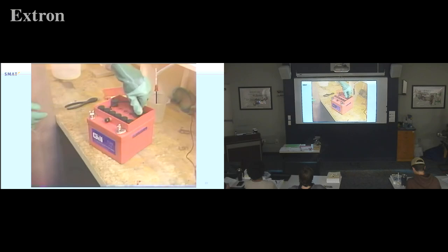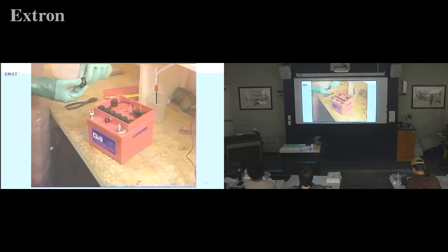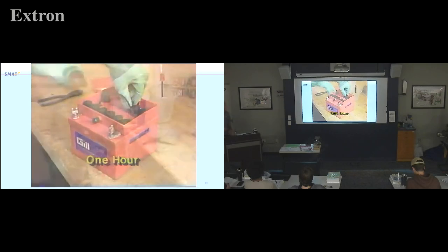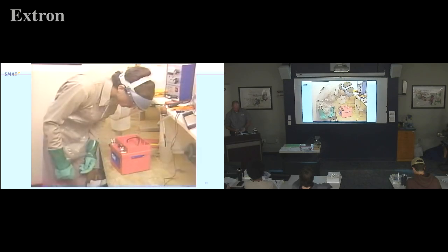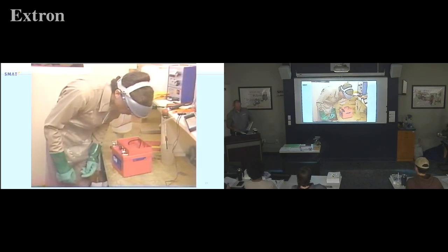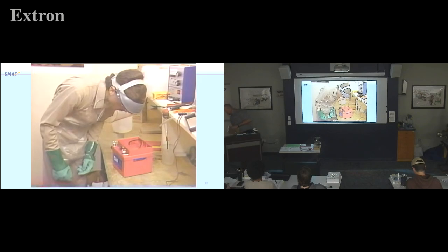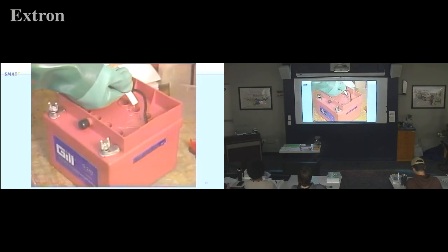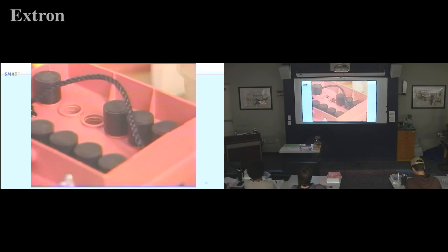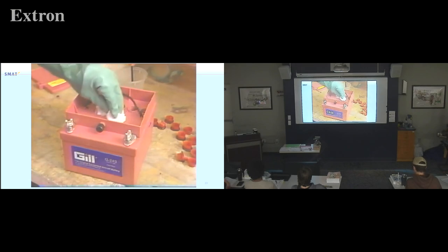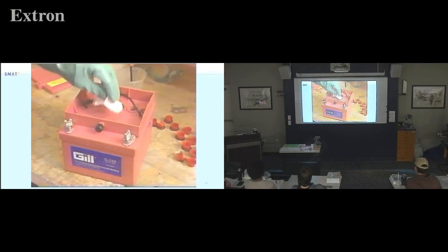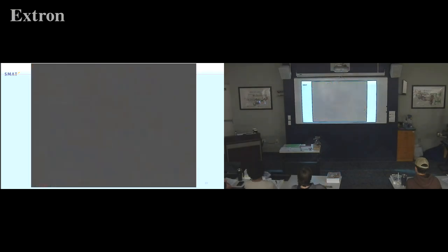After electrolyte has been added to each cell, install the vent caps and let the battery sit for 1 hour. During that hour, occasionally rock the battery from side to side to release any trapped air. Check each cell, and if the electrolyte level has fallen below the top of the separators, add electrolyte to restore the initial level. Be sure to replace the vent caps before charging the battery. If vent caps are not installed, the top of the battery may become sprayed with electrolyte, which will cause the battery to self-discharge unless the battery is thoroughly cleaned.